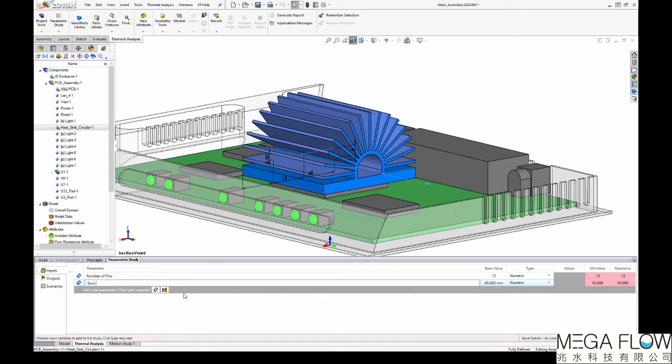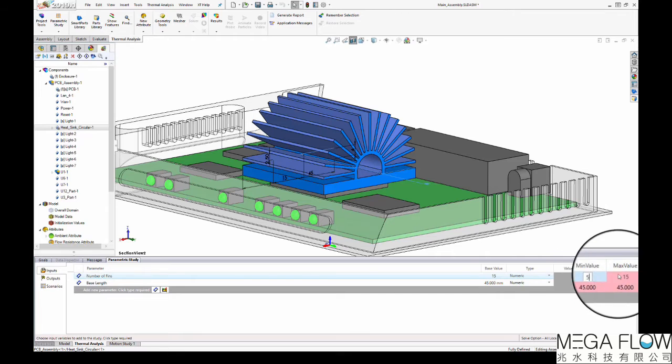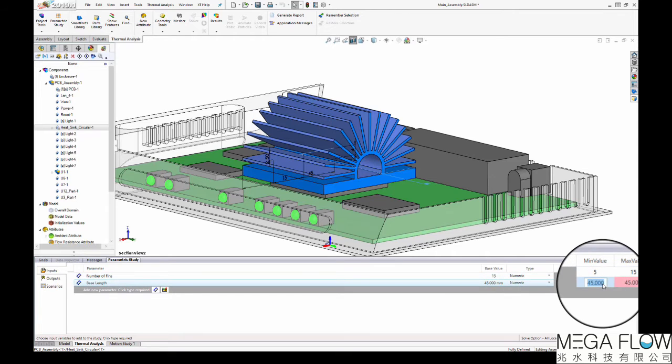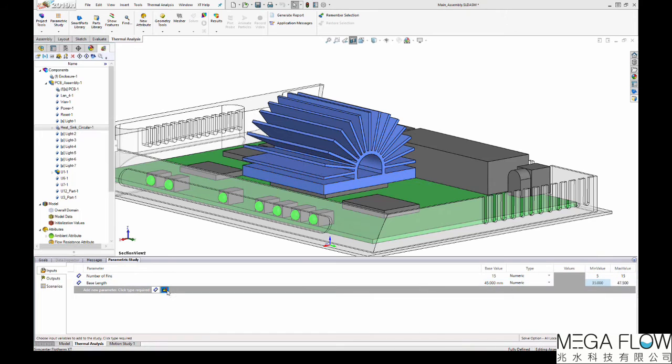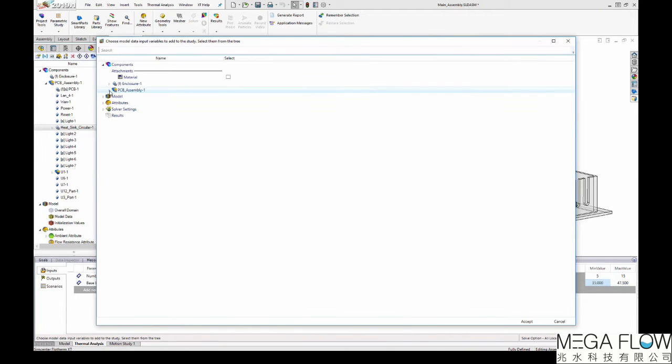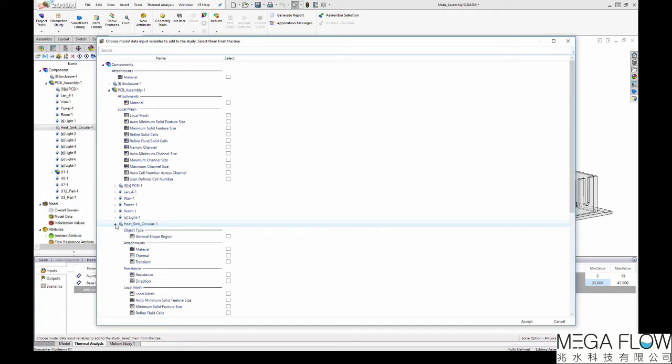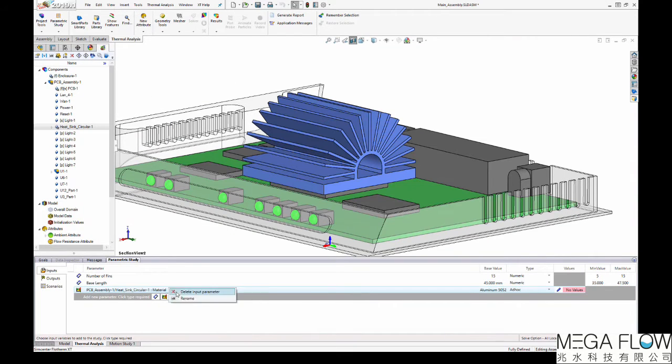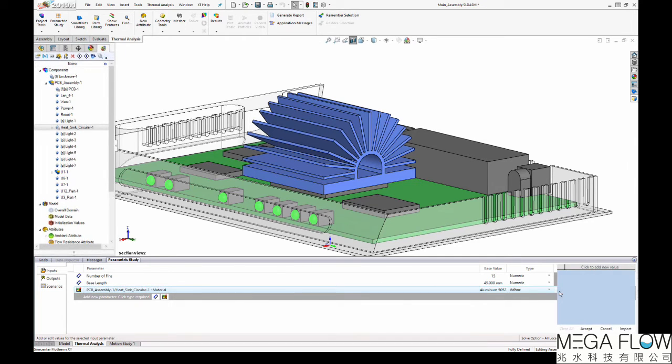Once the study has been activated, the user is able to set up the input and output variables for the study. For the input, you are not limited to numerical entries such as dimension, as a number of these external optimizers can accommodate input to say the material applied to a part. It is possible to define an ad hoc or linear step variation, as in the manual variation of a range as in DOE. Usually the output variables are left as just recording the value.